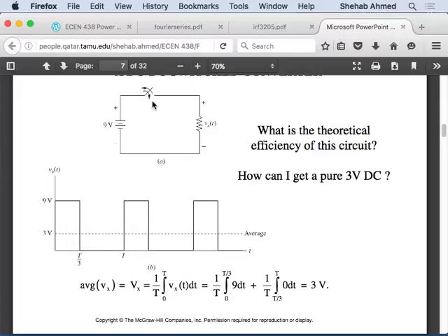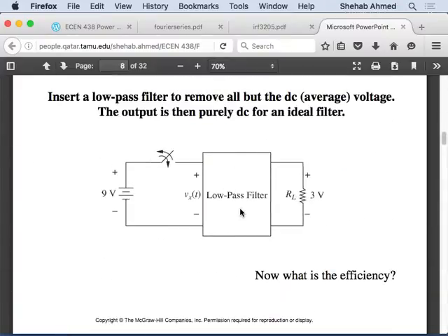Very, very large difference. So that's why in power electronics we talk about ideal switches a lot. The device is an ideal switch, because compared to what it would have been for a linear regulator, it's a lot less loss. So it's almost 100% efficiency. But now, if we add this filtering stage, there are losses in the filter.